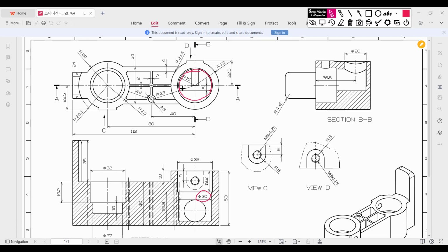After that I will draw a center line along this circle center point. Then I will offset another line of 5 unit here. Okay, offset another line of 5 unit here. Then the final circle will look like quite a semicircle. Okay, this portion, and after drawing this circular portion I will cut it to 26.8 unit. Okay, I will cut it to 26.8 unit.